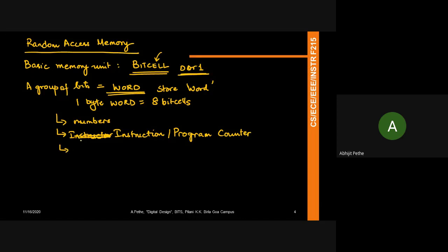We also use memories, obviously, to store alphanumeric characters. So floating points, alphanumerics, all those will require memory. As you know, if you want to store a simple integer, life is much simpler. When you want to go into alphanumerics or store floating points, you have to allot more and more bits to the word, or in other words, the word length keeps increasing.